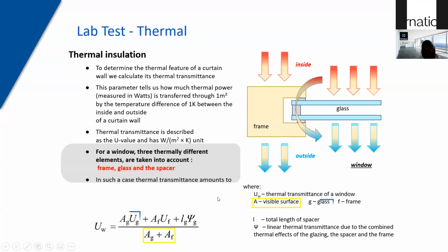consider. Many of the yesteryear specifications are always looking only at glass, but now more and more architects have come to the understanding that U value should be an assembly U value. So if you look at the latest codes in UAE and Saudi Arabia, they very clearly mention frame assembly U values.